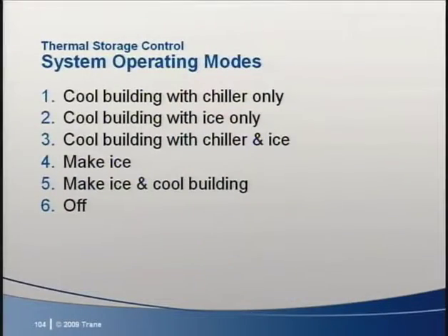First, controls cannot achieve performance the system does not support. It is very important that the design supports all 6 operating modes. Paul mentioned these earlier, and they are shown on this slide. How can you know that the system will operate properly in each mode? The only way I can prove it to myself is to diagram out each mode with temperatures and flows and pressures so that you know where the water is supposed to flow and that it will actually flow there.